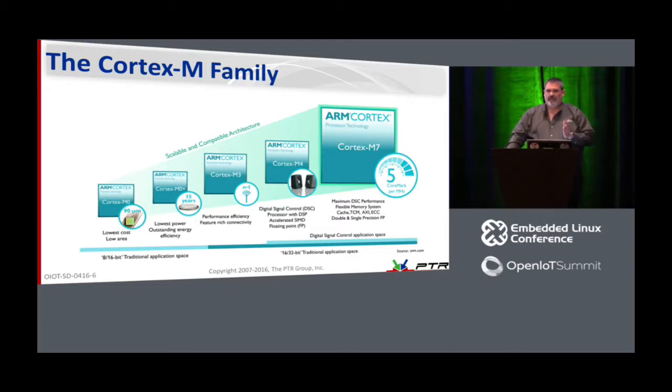It is a very small processor, however, and so when we think about processors like the Cortex-M, we can't think in the same terms that we think of when we're dealing with Linux. There is no memory management unit. The Cortex-M0 typically has something on the order of 32K bytes worth of memory and maybe 128K bytes worth of flash. So the way it operates is significantly different than a typical Linux machine as well, because what we find in the Cortex-M is that the flash is executable flash. It's like NOR flash. It's not exactly NOR flash, but it's like NOR flash in the sense that we can load our program into that flash and we will execute completely out of the flash. The RAM that we have is typically static RAM, and in this case is simply used for scratchpad memory. It's used for the stack, it's used for dynamic variables, it's used for anything that has to change while the application runs. That's going to be stored in the SRAM, whereas the actual program itself will be stored in flash.